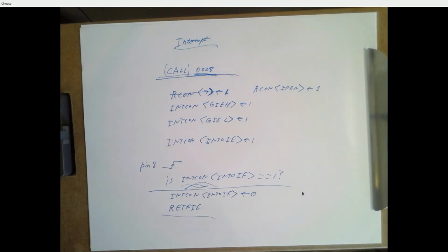All right, that sounds pretty straightforward, and in some ways it is, but the ways in which we can get tangled up with interrupts are enormous. There's a lot of things that can go wrong here. And because interrupts are triggered by usually outside events, there's no way to predict where we're going to be in our code when an interrupt occurs. Which means you might write code that works great 5 times in a row, and the next time you try it, it totally breaks, because you happen to be in a section of your code where the interrupt exposed a bug in the way you're handling interrupts.